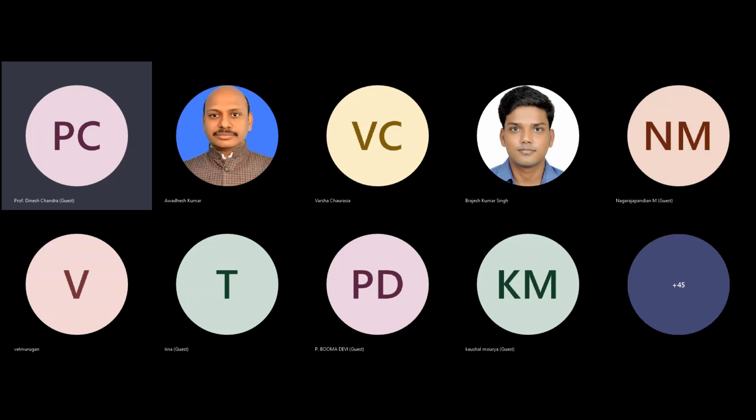The good approximation means that the reduction procedure should be computationally less time consuming, and it should be automatic also. But the Krylov subspace method will need intervention once you give the computer some initial values. This Krylov subspace method gives you the reduced order model. So it becomes fully automatic when we combine it with the Padé approximation or some interventions into this method. These things are under research these days, how to convert this moment matching, which is fully automatic, to a Krylov subspace method and so on.